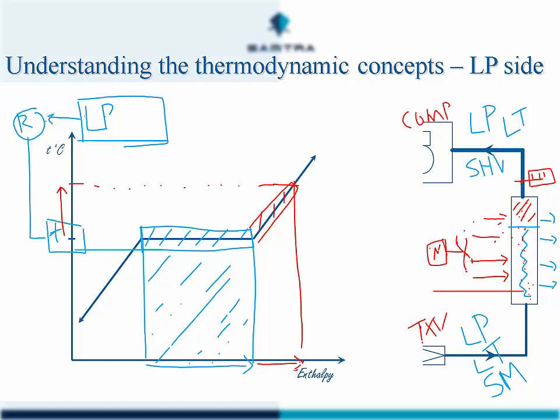So just to recap quickly, we use the low pressure gauge, and it has to be the absolute value. We go to our vapor tables, and from our vapor tables the corresponding temperature will be our saturation temperature, and that temperature is running along the horizontal line, the line inside our evaporator.